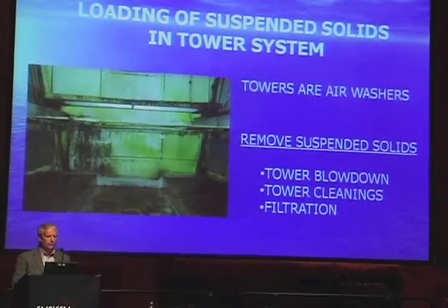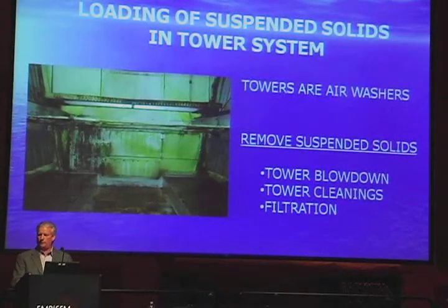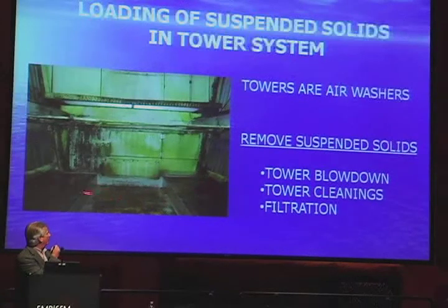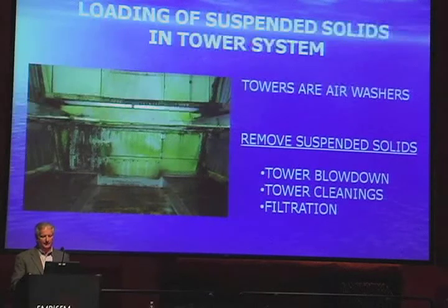What we want to do is make sure that we remove or reduce the amount of loading of particulate matter, because it's also a transport mechanism for biological activity. It's like they hitchhike, grab a ride on it, and they go around the system until they want to settle out somewhere. And of course, you can see the cooling tower base and all the mud and debris and everything else that accumulates in the cooling towers. So in order to remove suspended solids, you have a couple options. One, you can do more blowdown, which is against the thought process of trying to conserve water. You can do more tower cleanings, which is certainly recommended by OSHA, or you can look at filtration.